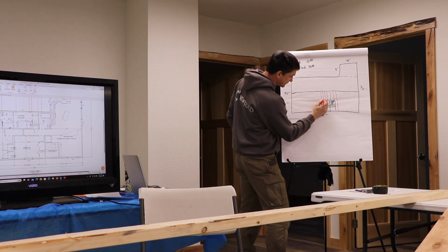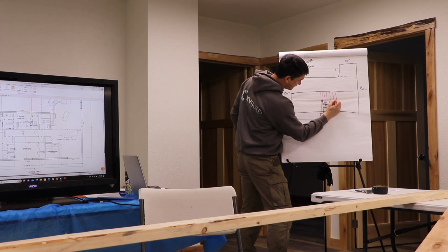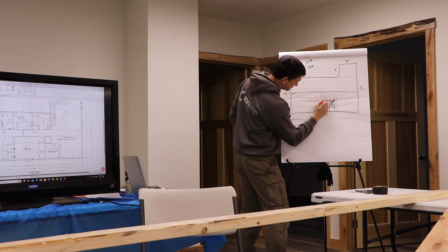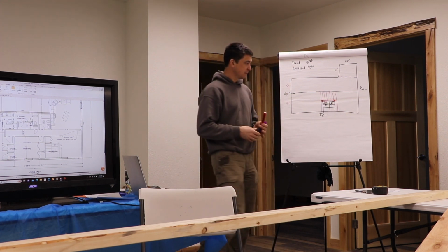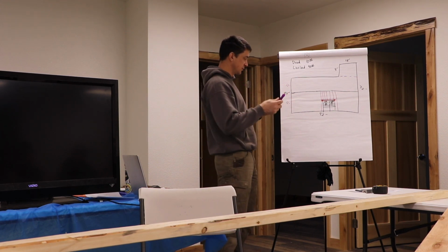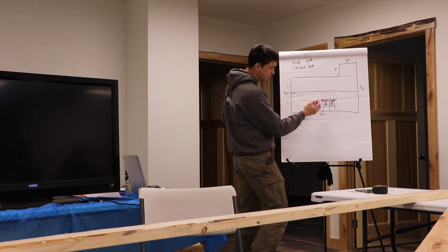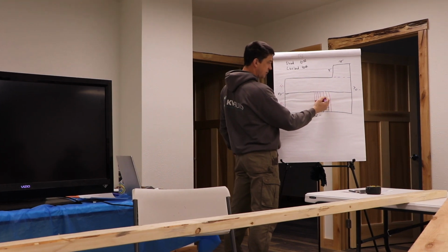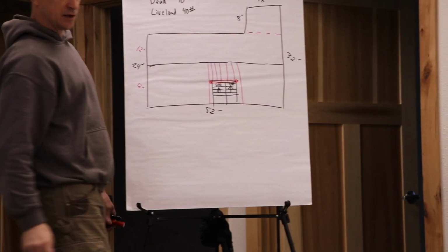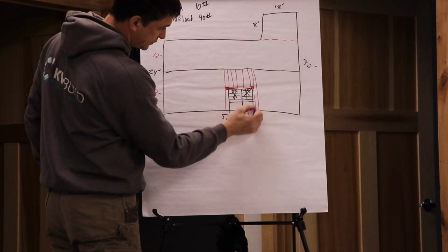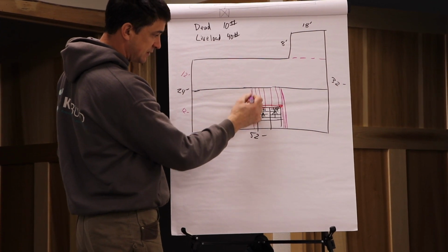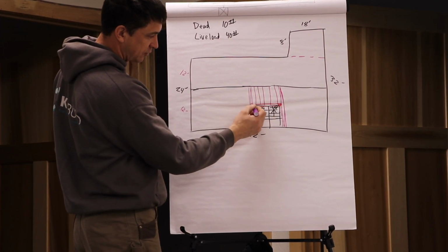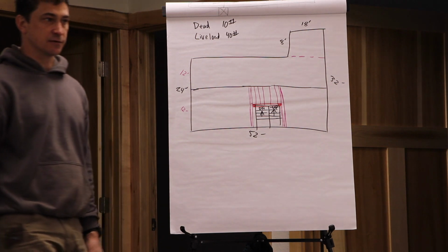Okay, so Justin says we can put a post here and a post here, and we can run a beam across. That makes sense? That's a great, simple solution. I'll show you guys another possible option. We could run the numbers and see how much load this is going to be and how much load will be on that beam. And then we could just put in whatever we need here. Maybe we need 2, 3 plies of this floor joist, and we could throw a hanger and just hang the beam off to either side.